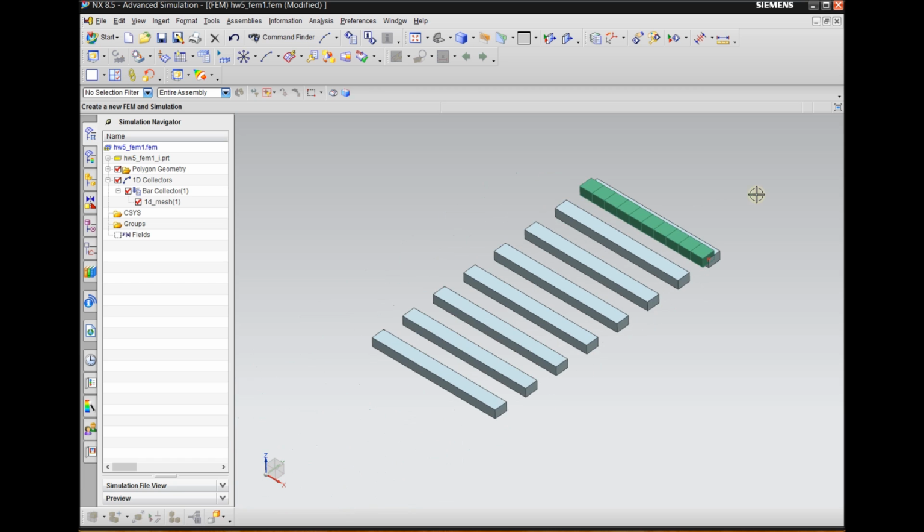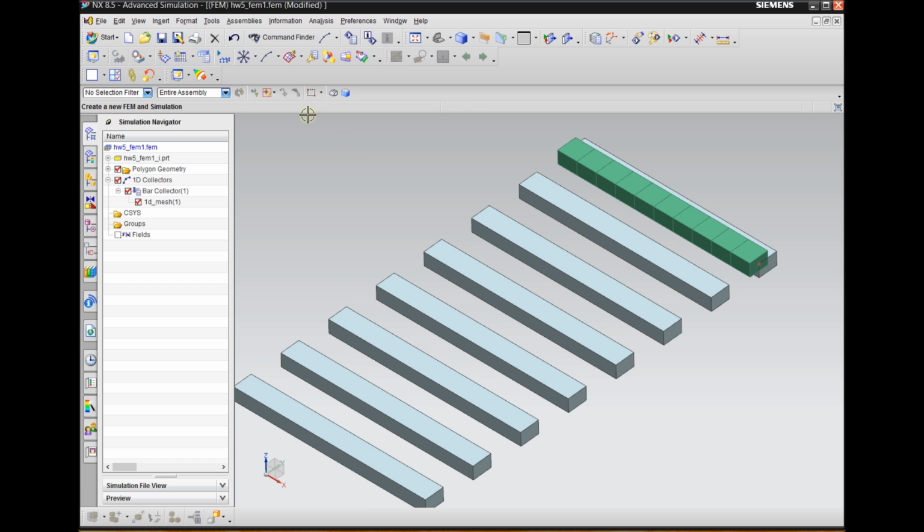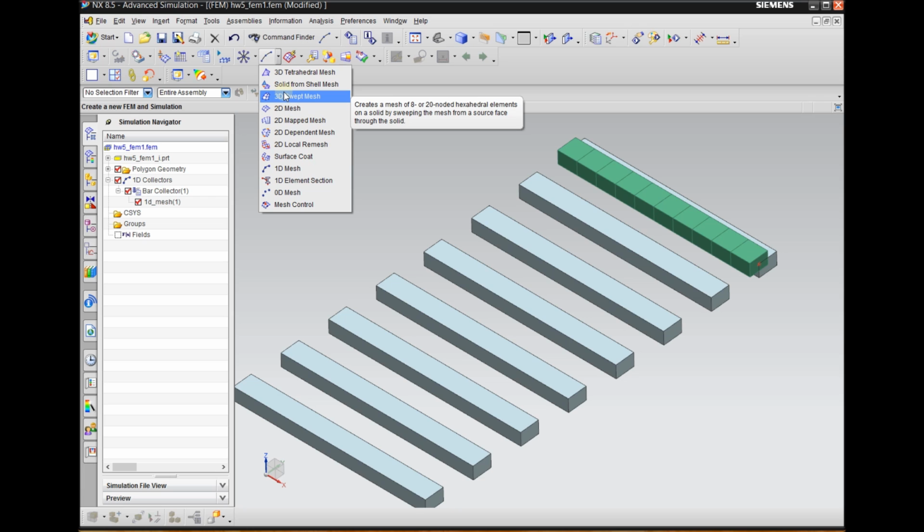Okay. Alright, the next beam is going to be a 2D mesh, and we are going to use the triangles. We have linear triangle and parabolic triangles, as well as quad. We're also going to use quad elements like linear quad and parabolic quad. So we have 4 2D meshes, and let's start with 2D mapped mesh. So for 2D mesh, we're going to use this method.